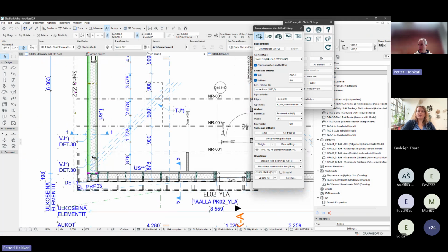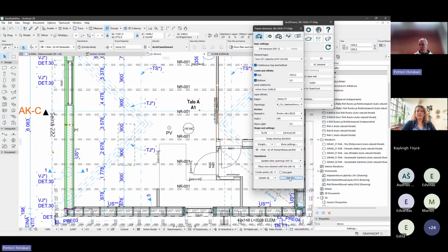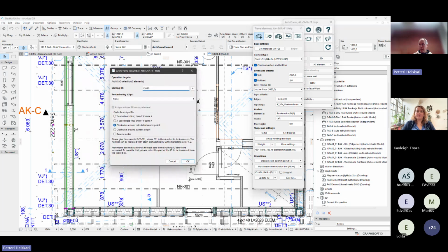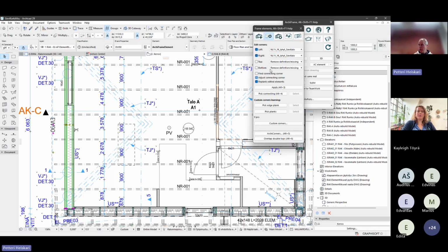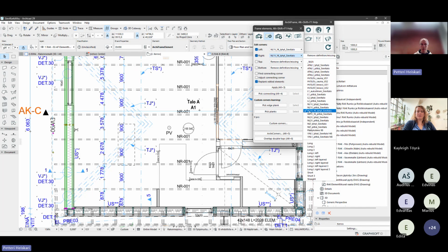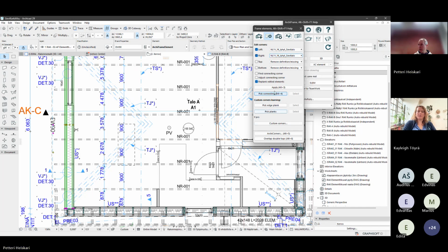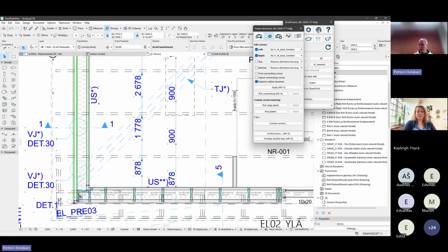And now we got the first phase, the placeholders for the real structure. And here you see there is a random ID. The architect hasn't paid attention to the wall IDs because it's not part of his or her job. So this is the latest phase to give IDs to elements. So I say this external wall 90. Then set the corners to one of the presets that have been taught to ArchiFrame earlier. And we get these layers compatible with this existing corner.